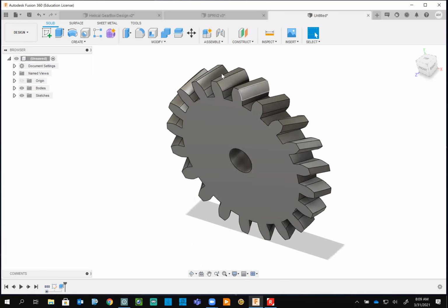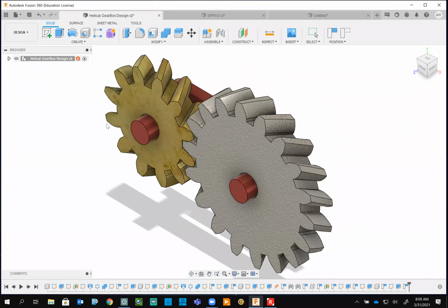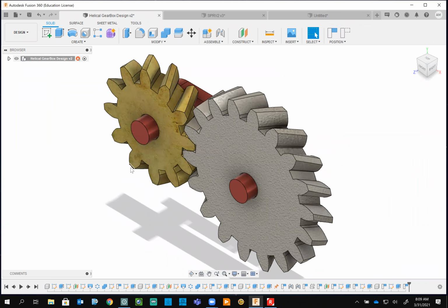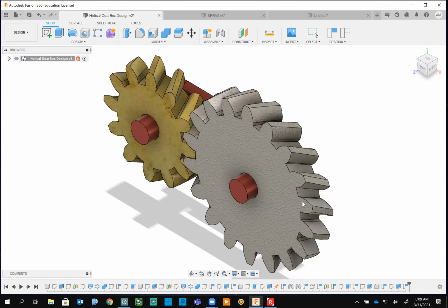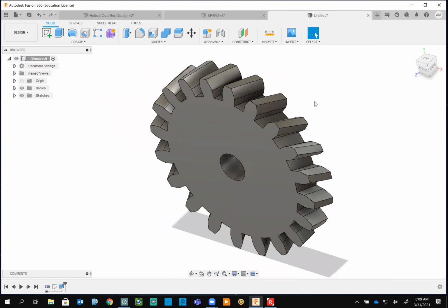And of course, if you want to make a gear in a pair, you make another one like that. And like me, you install it there. And then the software shows you if they mesh. In other words, if your design is good and they are working together. For example, if I make 2 gears, but their modules are not the same, remember the pitch or the module must be the same. But intentionally, you can try it later, if you pick the number of teeth, some arbitrary numbers, so the modules are not the same, then you will see it's going to be crazy and these things are not going to mesh properly.